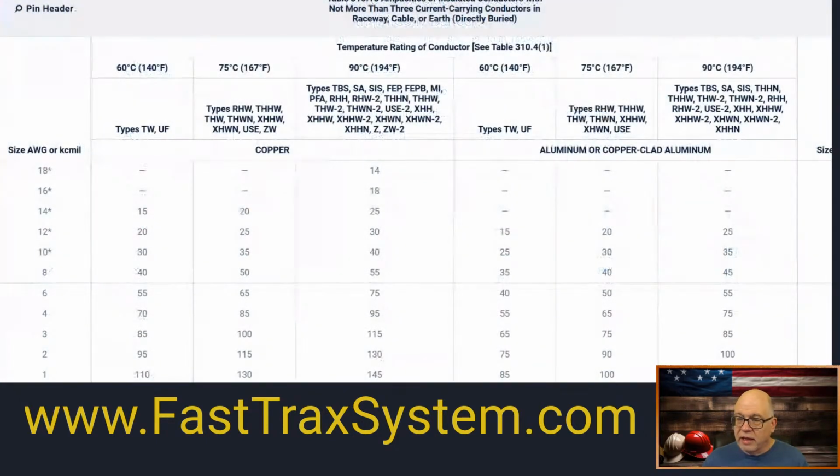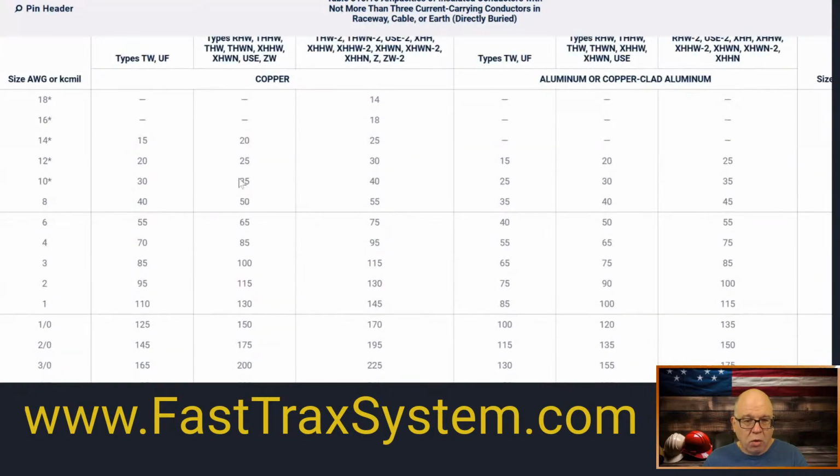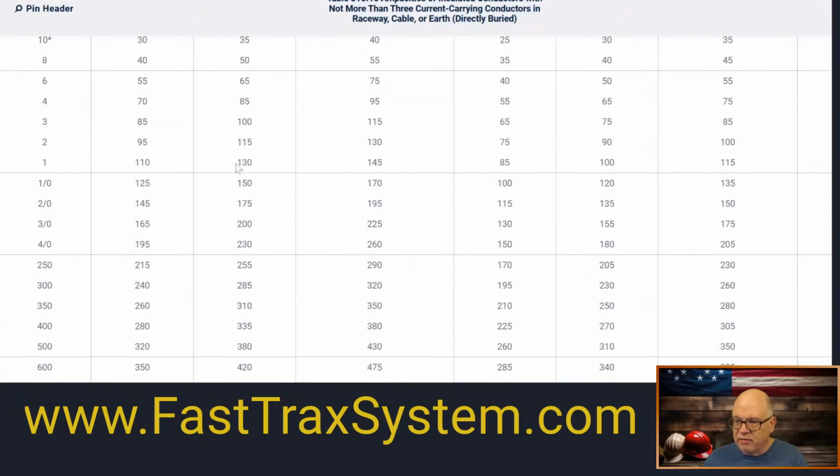So here it is. And okay, so in our case, we're obviously over 100. We didn't say the conductor type, but we're saying all the terminals are rated 75. The wire is going to be a THHN/THWN-2. So meeting all the rules in 110.14(C), we're going to be in the 75-degree column. And we need to have something that's going to terminate on that overcurrent protective device. So in this case, I would do a 1 gauge copper, that type of thing.